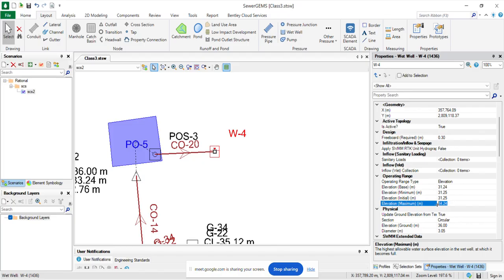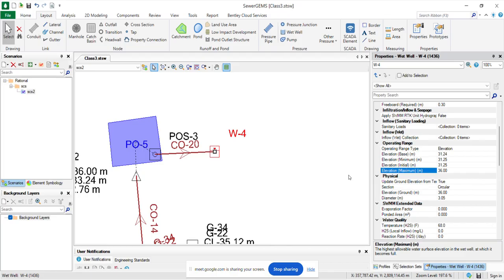No need to fix it for 34, because if you fix it for 34 it will come until the tank itself. So we will be fixing until the cover level. So 36 is the maximum. Inside this only the pump is going to be there. But in the model we're not able to make it inside. We're going to make it outside of the wet well only. So for that we'll be installing the pump here.